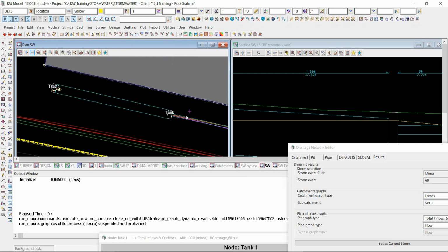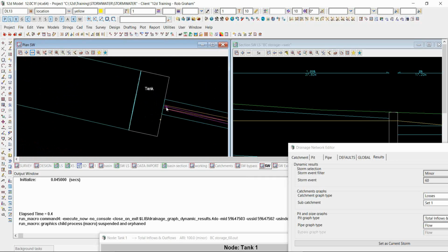Now, if I go down to my other structures that I have down here, a weir would never use a KU value, okay, because KUs belong to conduits for pipes. And nor would the orifice, because the orifice is controlled only by the discharge coefficient. However, we did have that 100 millimeter pipe. And that 100 millimeter pipe will have some entrance loss as the water comes through. So I guess in your answer, putting in a small KU value just for that 100 millimeter pipe might be a good idea.